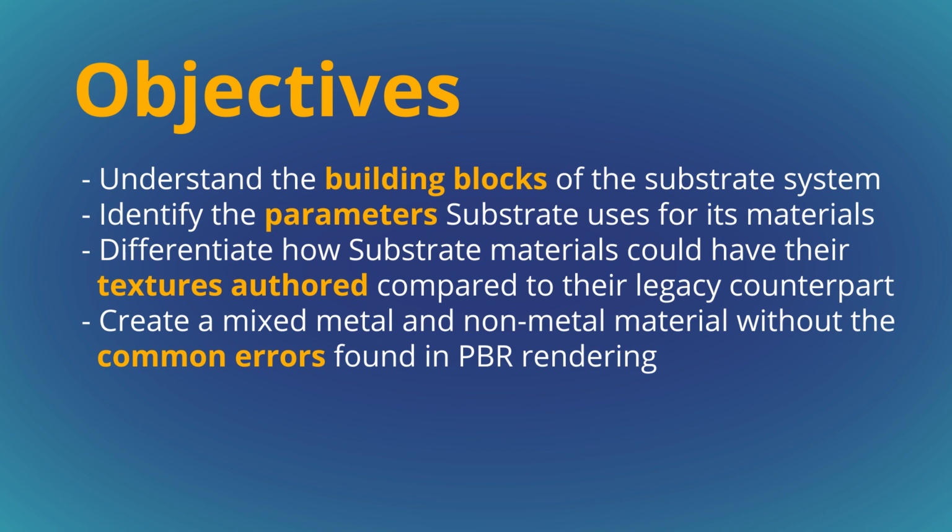So some of the learning objectives are going to be to understand the building blocks of the substrate system, identify the parameters Substrate uses for its materials, differentiate how substrate materials could have their textures authored compared to their legacy counterparts, and then finally to create a mixed conductive and dielectric material, so a metal and non-metal material, without having all the common errors that we would typically see when doing that in a PBR renderer.